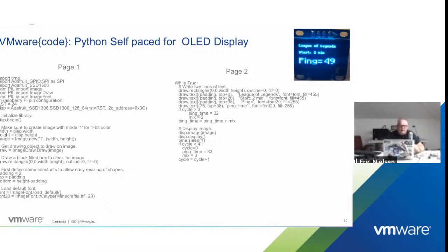That's part of Python. It's part of the Raspberry Pi. You don't have to go get that. The only library you need to go get is the Adafruit SSD 1306. Once you have that, I'm going to then create a display. The RST 24 says this is how to interface with the pins. There are, I think, 24 I/O pins out here. That's the model type for it. So this is another way to interact with the pins.